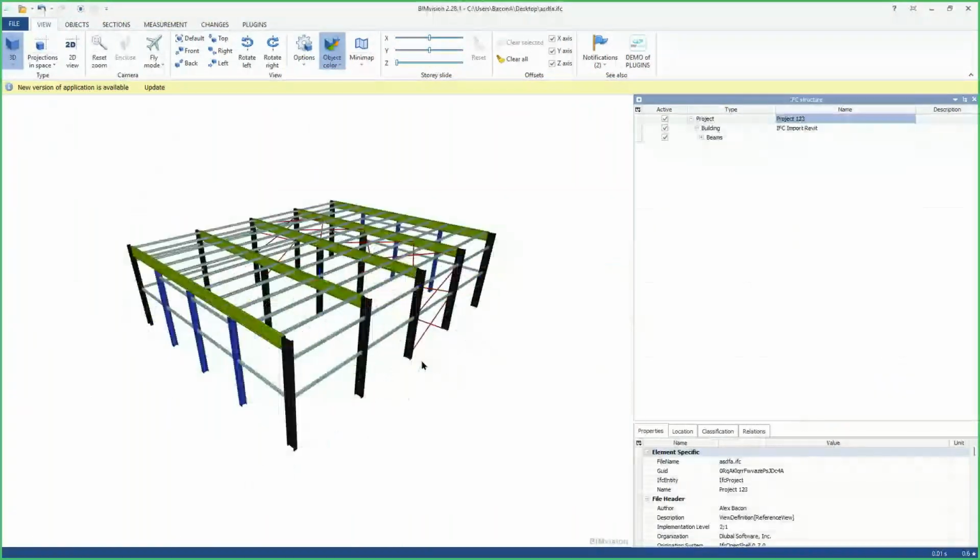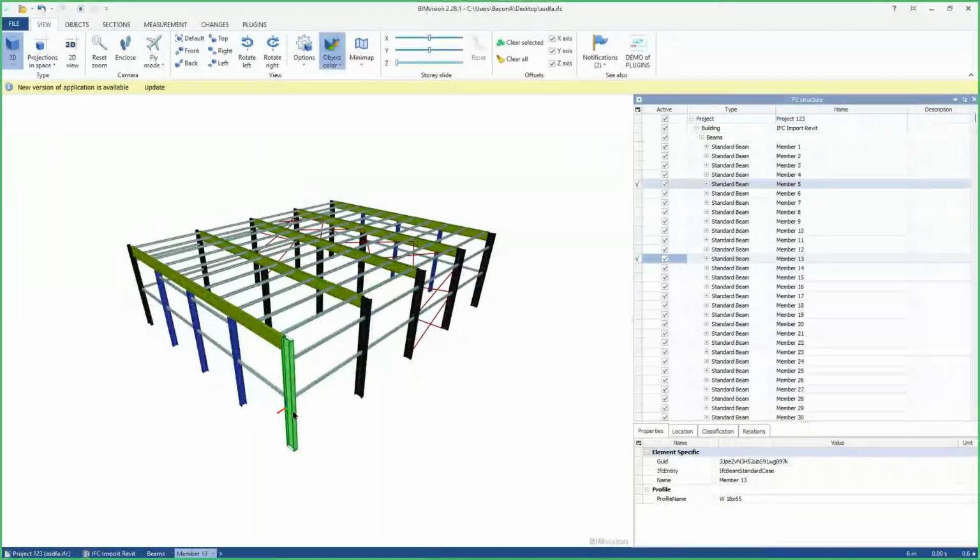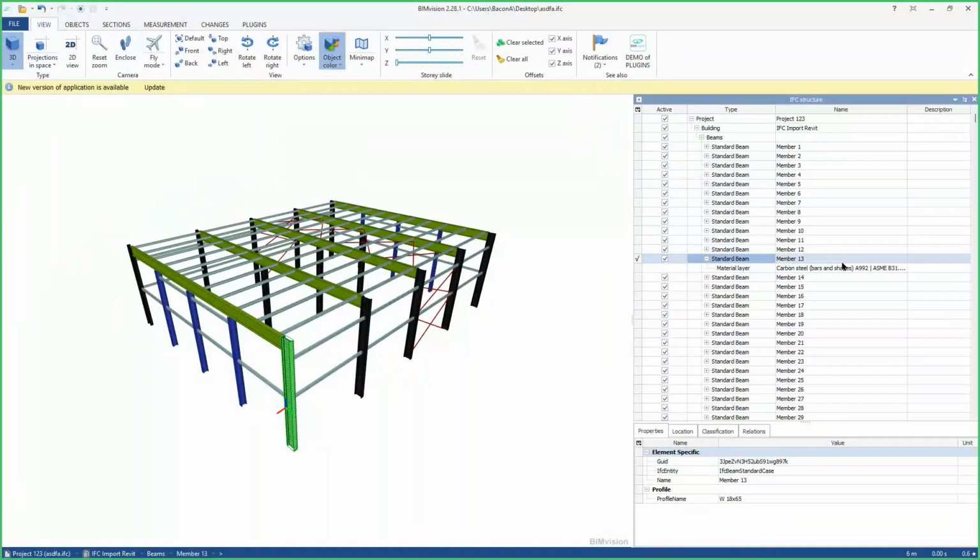And yeah, this is the file from RFEM that we just made. And I can, again, click on the member, and I can see that material info and section info saved within that file, along with the same GUID here. And the good part about this is that because we saved that info in the IFC, we can use that info again, like I just did with the export. And the members, like I said, save the GUID. And this is good because it allows all of us to compare IFC files. If we have two IFC files where the GUID of the objects is the same, this will allow us to compare sections and materials, which is good.